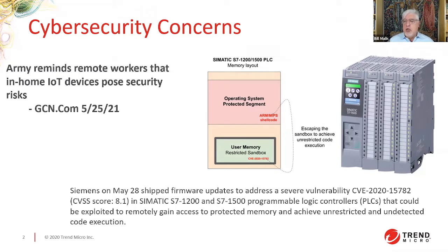The more serious note on what was reported in yesterday's news was the fact that last Friday, Siemens published an urgent firmware update because it turns out that 2 series of their PLCs had a high severity vulnerability, which would allow, the diagram is on the right there, code to escape the sandbox and run undetected on board the PLC. So those of you who are running Siemens PLCs of this model, the S7-1200 and the S7-1500, should probably take a look at updating the firmware for that.